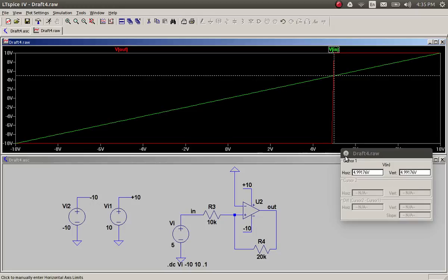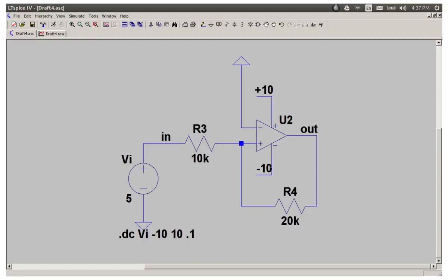Yeah, around 5 volts. So how do you determine this resistor ratio? I'll just explain this once more. I look at the negative voltage, minus 10 volts, and think of this as a resistor divider. I'm going to design it now. I have this resistor that I don't know, and I have 10k, and this gives me a voltage, which is, everything in k, 10 divided by 10 plus R.